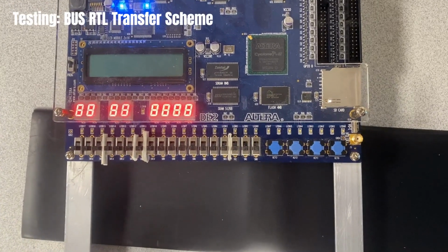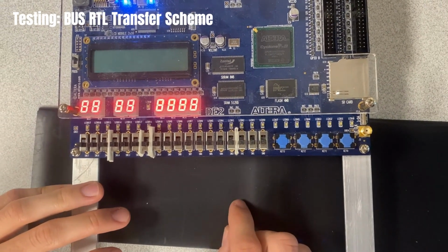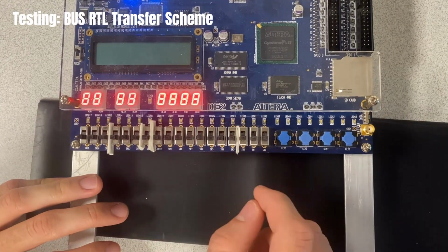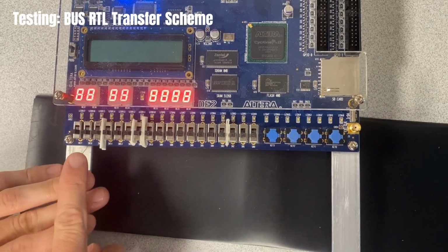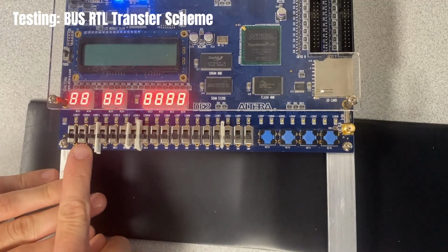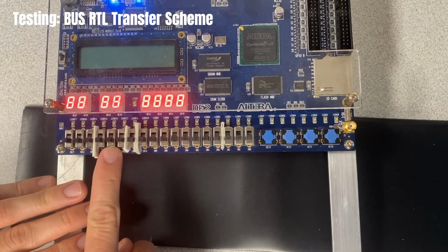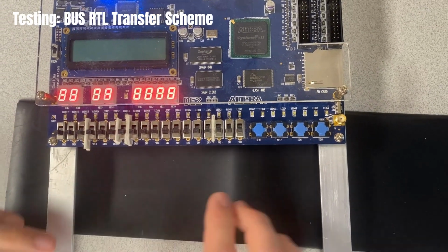Alright, this is the 3-bit bus RTL transfer system with 3 3-bit registers. So I've got the 3 registers shown in the red LEDs here, and the bus will be shown in green here. I've got my input switches, and then my control signals. These switches are for writing from the registers to the bus. These are for reading from the bus to a register, and this is for putting the input into register A, just so we can get a number in.